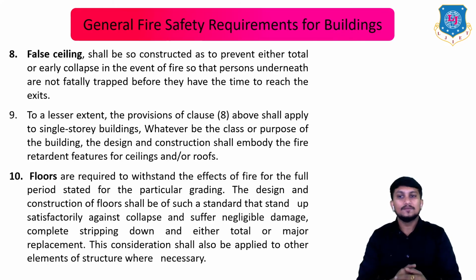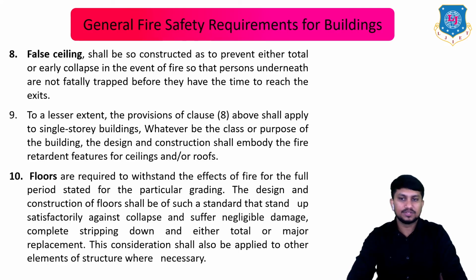Okay, next is floors. Floors are required to withstand the effects of fire for the full period stated for the particular grading. Okay, as we have studied, the number of grades have the number of hours of time to escape. Okay, the design and construction of floors shall be of such a standard that they stand up satisfactorily against collapse and suffer negligible damage, complete stripping down, and either total or major replacement. These considerations shall also be applied to other elements of structure where necessary. Okay, the floors should be constructed such that, based on grading of the building, they resist the fire.